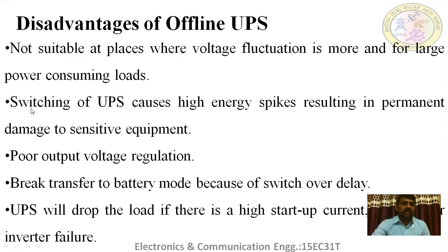And the second disadvantage is that switching of UPS causes high energy spikes, resulting in permanent damage to sensitive equipment. In the basic operation, when the mains power drops, it is required to initiate the UPS or turn on the UPS to start the function. So during the switching or during the turn on of UPS, there is a chance of high energy spike, surge voltage. That voltage may cause some sensitive loads to be damaged permanently.